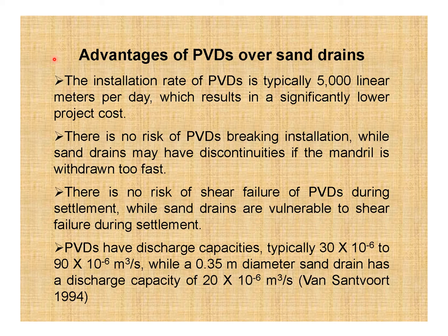Now this topic is also very important, that is the advantages of PVDs over sand drains. We have discussed the sand drains and the PVDs. The installation rate of PVDs is typically 5,000 linear meter per day, which results in a significantly lower project cost. This is a very good point.